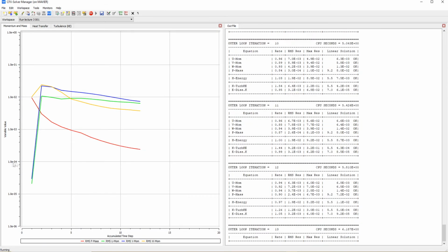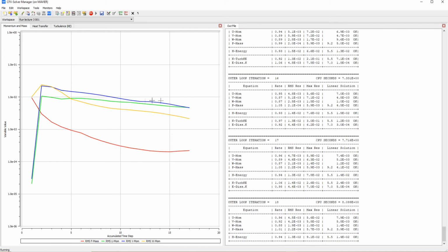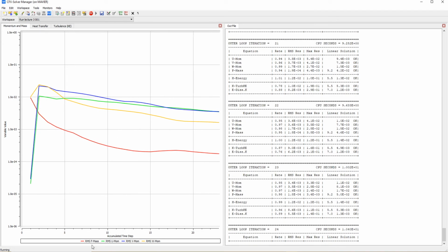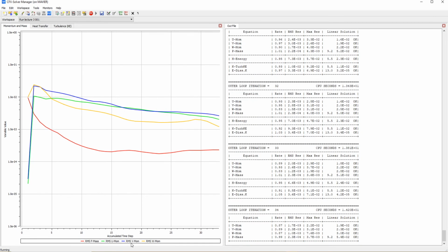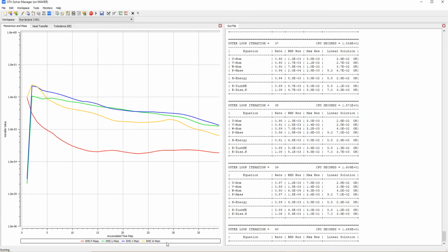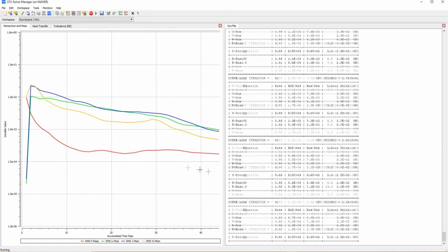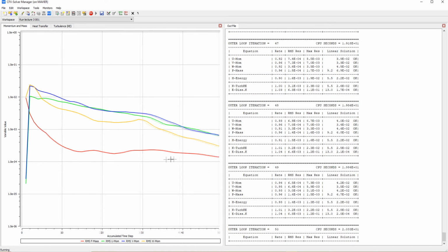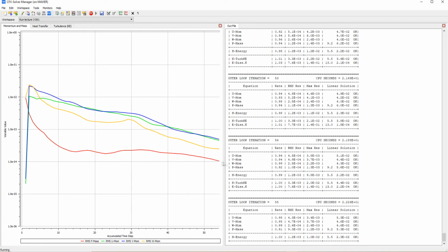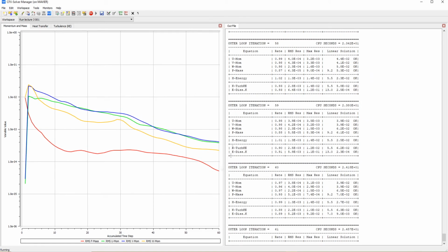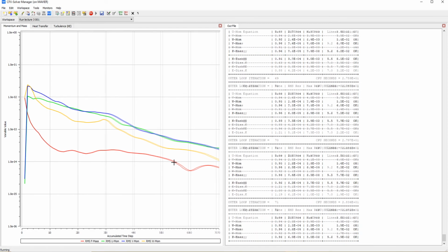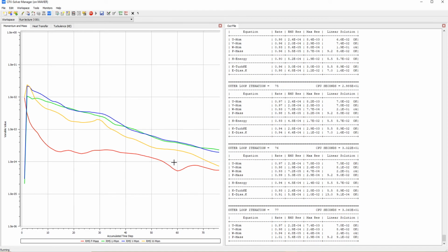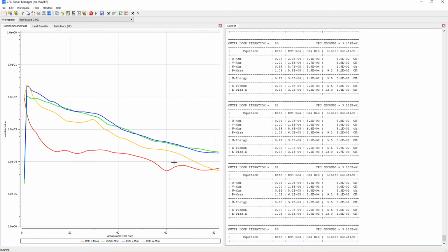You can see that we didn't change the convergence criteria. So as soon as all of our curves, the RMS P-Mass, RMS U-Mom, the V-Mom, and the W-Mom, go below this line right here, 10 to the minus 4, the simulation is gonna stop, and it's gonna tell us that your data has achieved your convergence criteria, which was 10 to the minus 4.